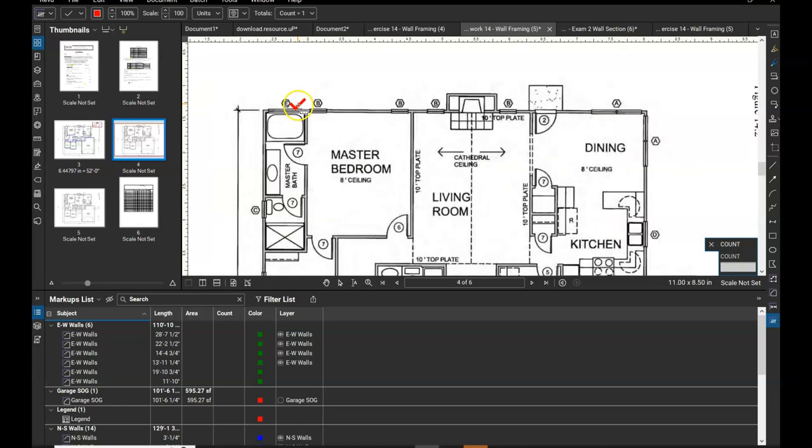And I just like putting in one of them for my wall intersection, just so I remember that it's 3 studs per intersection. I'm going to use triangle. 3 points, 3 sides. Whatever you want, but I'm just going to bring down the opacity before I get going to like 60 maybe. It gives you the preview. That looks pretty good. So you can click on even a few, but we're really going to count all of our corners and every time a wall intersects another one.